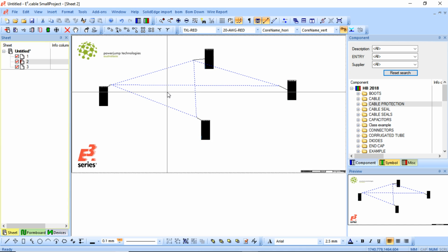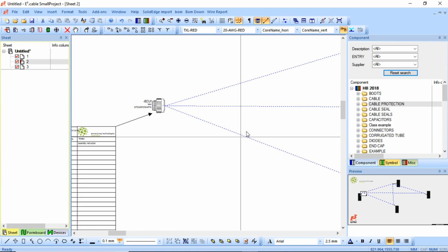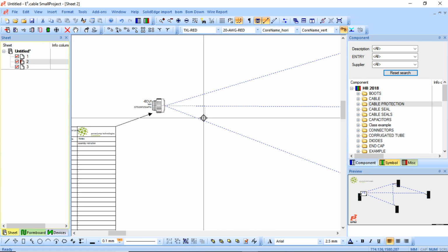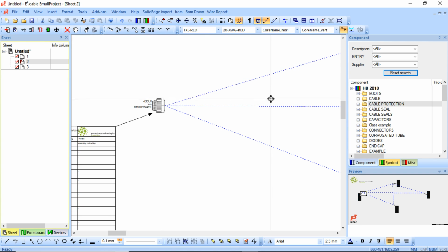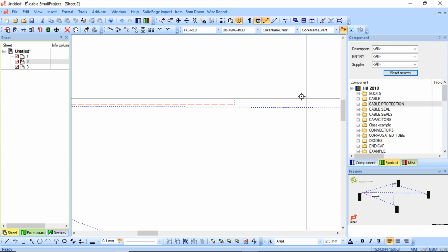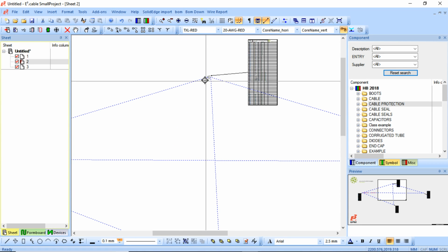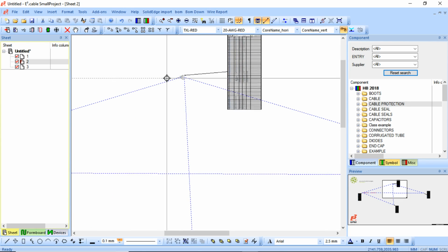So again, you can actually start from a harness drawing, work towards a schematic or a topological, or the other way around, back and forth pretty easily. So once I've just placed my connectors pretty simply, what I can do is I can start to draw a segment. If I just press my connection tool, I'll just place a segment here, and then I will go find this one. I'll just do an angled connection to this one.